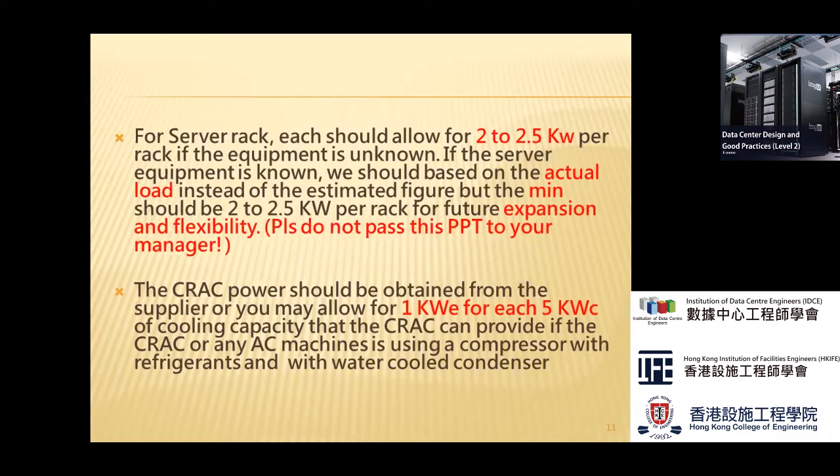You don't know the actual power required. But if the server equipment is known, of course, we base it on the actual kilowatt or watt from the catalog of the equipment instead. If you don't have this data initially, you can take the minimum of 2 to 2.5 kilowatt per rack, or add more, say 4 kilowatt per rack. It's up to you, for future expansion and flexibility. But don't overestimate and don't underestimate. That's the difficult part of it.